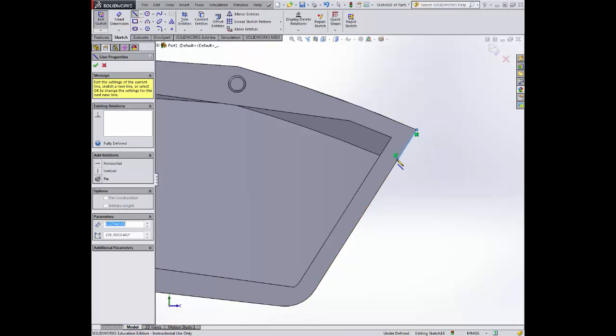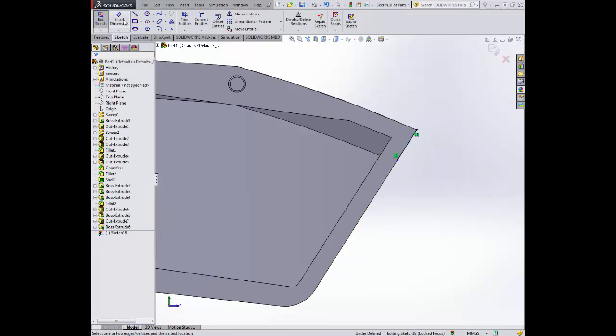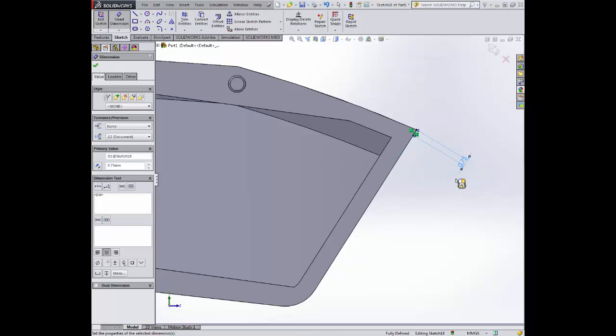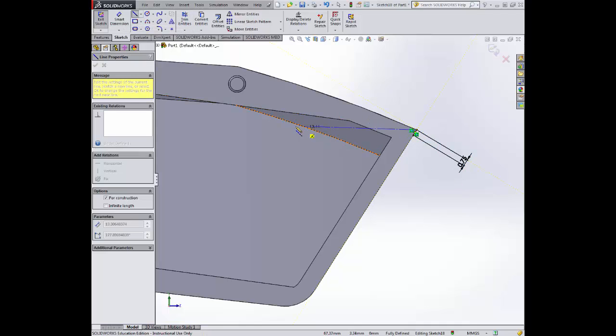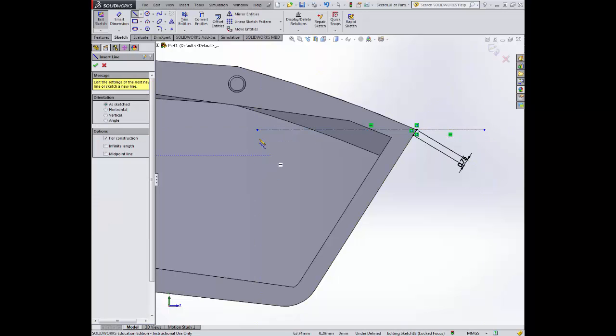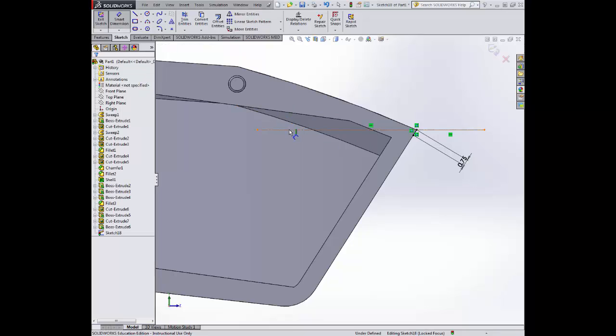So going along the edge as we have done previously. Smart to mention that. Again, making sure it comes out at 90 degrees and not at any other angle. 0.75. Centerline tool. Top edge. We want this to be parallel, so what we're looking for is the yellow line tells us. As you can see, that white line is not. So I'm struggling here to find the parallel, and it has to be parallel, so let's try going the other way. Okay. Because it's centerline, it won't affect what we're doing, and because we've now got a line to form off, we can then draw off that line.